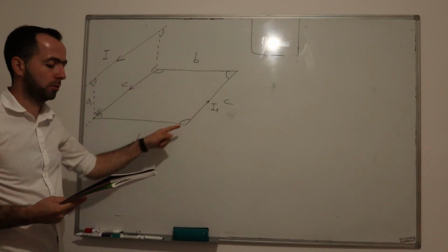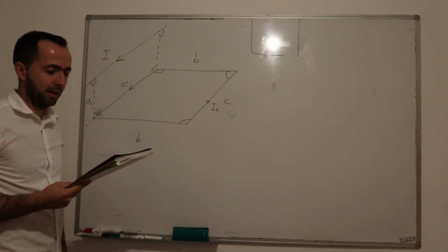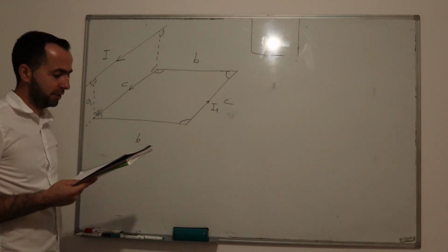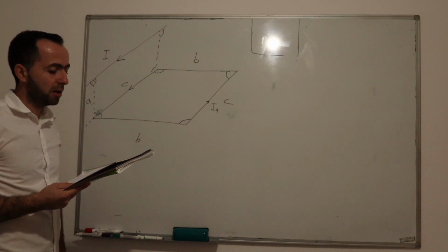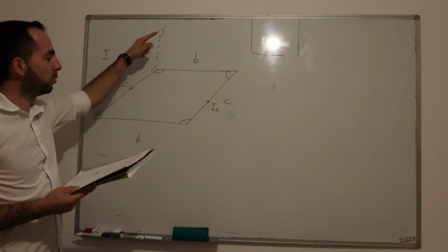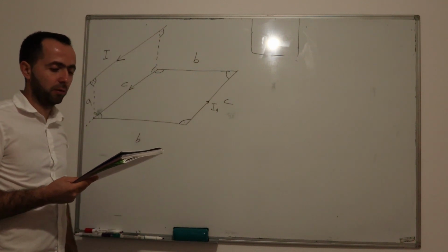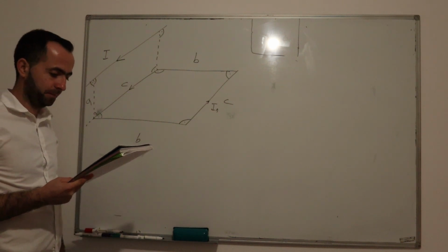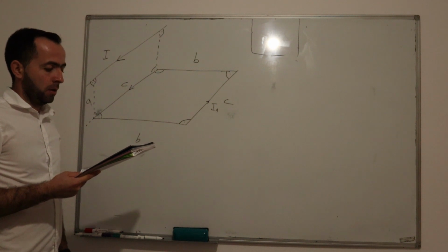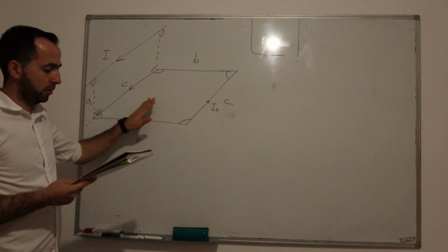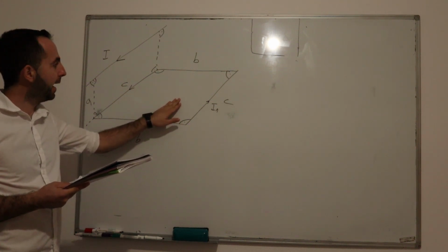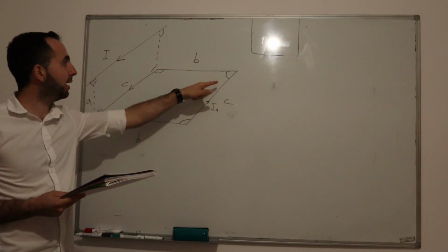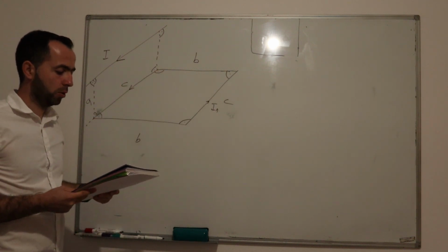The task: a rectangular contour is given with dimensions b and c. It is placed as shown in the picture, parallel to the infinitely long conductor with current I. Determine the flux through this contour and the magnetic forces on each side of the contour.